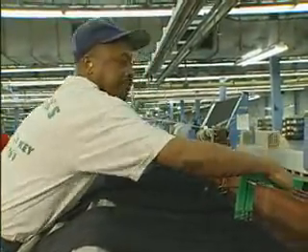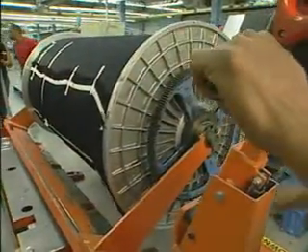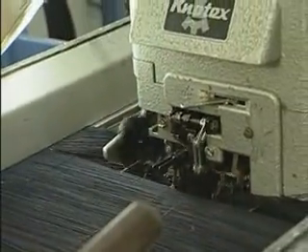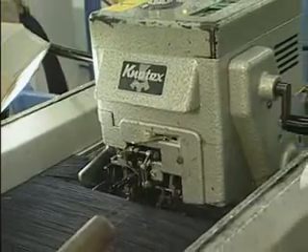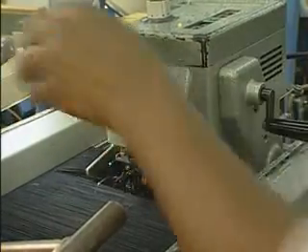When changing warps on a loom with an identical drawing-in draft and warp end count, a knotter may be used. The knotter will tie the new warp ends onto the warp ends already present in the loom. The knots can then be advanced through the drop wires, heddles, and reed. This manual procedure to replace a depleted warp with a new identical warp can take less than 1 hour. The changing of the draw to a new one is considerably slower.